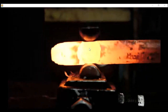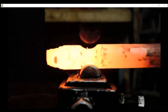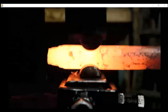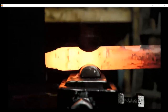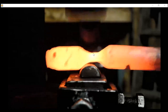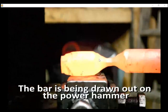Then this is fullering. The fullering here, you see this is a convex shape. With the convex shape, you hammer the work and reduce the cross section, and redistribute the material in the part. This is fullering, a convex shape. If it is concave, then this is edging. This is a mechanical hammer, automatic, not a hammer by hand.